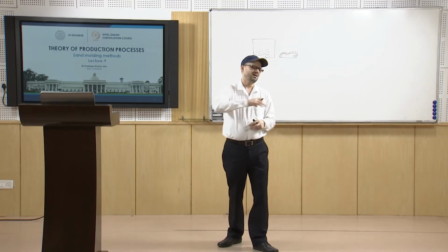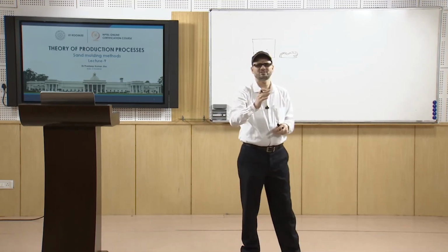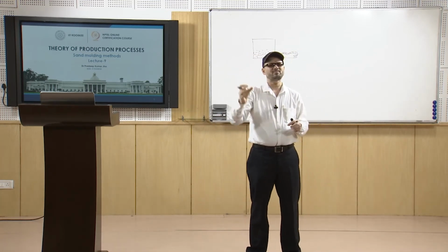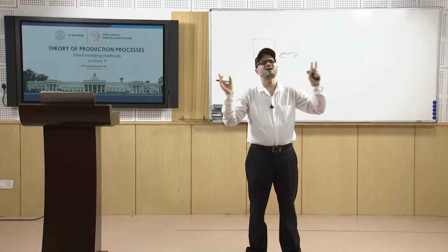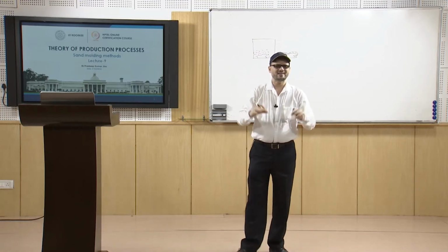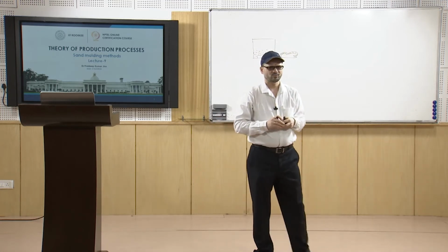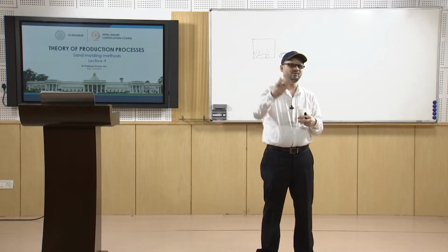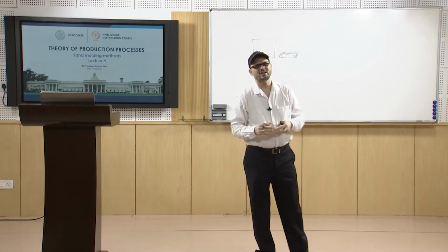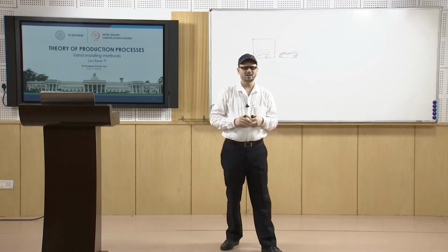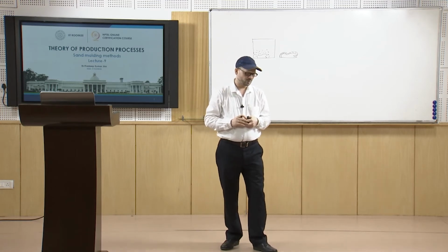You have the pattern making also of the shape by the use of skeleton patterns, or so you make large heavy cavities, and then you do the casting. Loam molding is similar, and is used for very large types of castings. There is also a carbon dioxide molding process.